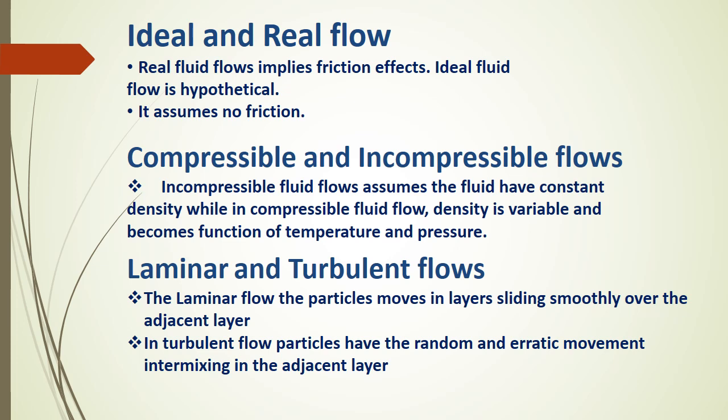So first, ideal and real flow. See, ideal flow is an imaginary flow, that means hypothetical, whereas real flow implies friction effect. Next, compressible and incompressible flow. The incompressible flow assumes that the flow has constant density, while in compressible fluid flow density is variable and becomes a function of the temperature and pressure.